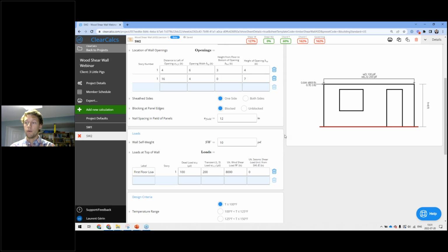The reason we do that is because the latest design standards are mostly based with wind loads being at the LRFD level already. So if you were designing this using LRFD, your load factor here would be 1.0. But to take this down to the ASD load level, we multiply it by 0.6.